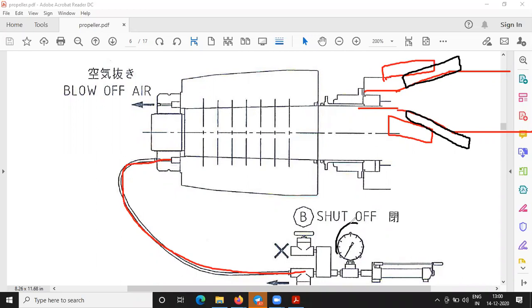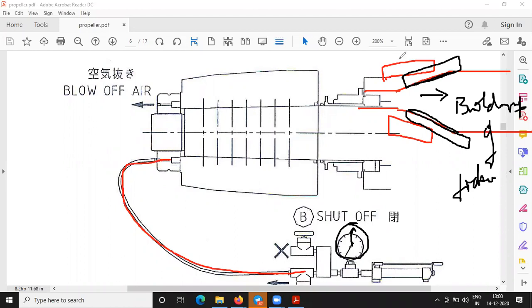Only when the pushing is complete and there is no further movement possible from the normal pressure of the oil, that time you will start seeing the deflection in the gauge. And that time you have to ascertain that, yes, now the push-up is starting and there is a building up of friction in between the propeller boss as well as the tail shaft.